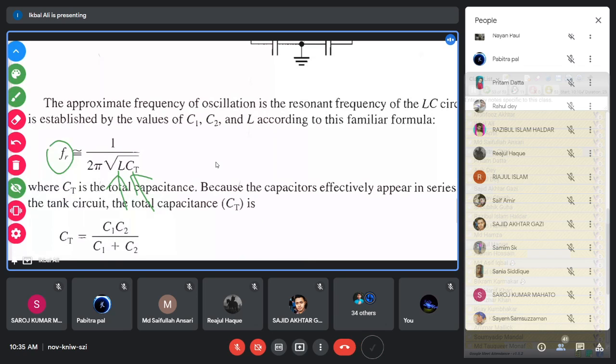So for this reason, you are putting very low values here in the denominator. So what will be the frequency? If the denominator contains a very low value, the frequency can go to a very high value. This is the reason: the inductor and capacitor by nature can have values lowered to a very low value. That is why this oscillator, where the beta network is composed of inductor and capacitor, can generate very high frequency, which is not possible if the beta network contains a resistor, because the resistance value cannot go below 1 ohm, which is almost zero resistance.